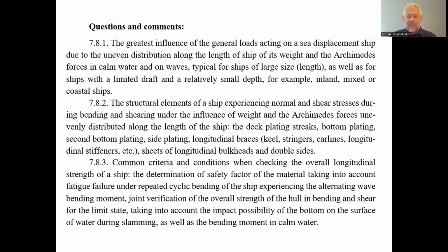The action of slamming could result in the loss of strength due to fatigue failure of the ship structures. This leads us to adopt the safety factor for the permissible stresses, a safety factor to exclude the possibility of fatigue failure due to the repeated impact of water on the bottom of the ship if we do not keep the trim.